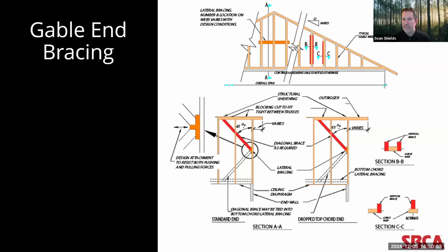And I should note, it's really difficult to provide a prescriptive detail for every condition. And that's why this kind of gable end bracing really is under the scope of work of the building designer. They're the ones who have to specify the specific bracing requirements, because the truss designer, again, is not going to be aware of the forces that are involved at this end of the building.